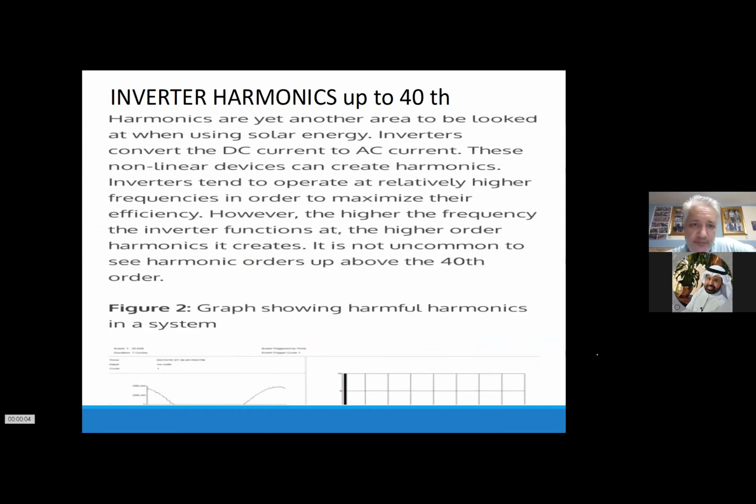As described, you will encounter some harmonics. I had one case now in Vietnam. They forgot to earth the transformer. It was visually earthed, but the cable was lying in the trunk, and it was not connected on the other end.